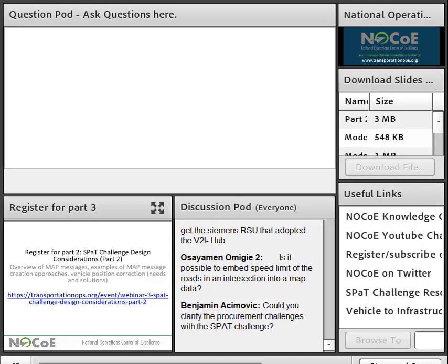This is Patrick. I'll answer that one. There is extensibility built into the J2735. That's what's called regional extension. So a region such as North America or Europe, or maybe even a state, for example, can add their own extensions. And Europe, for example, has added some extensions to their implementation of SPaT. The speed limits, I believe, are in there. They're part of the map message. So you can include the regulatory speed limit as part of the map message.